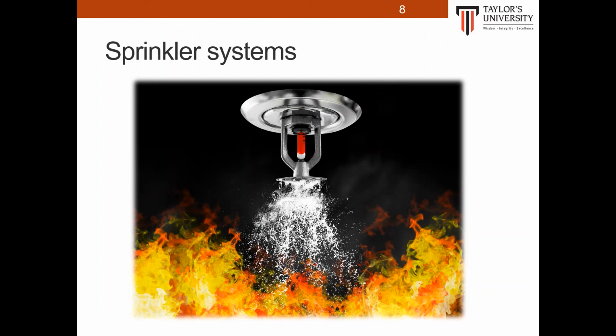Another approach activates the entire sprinkler array from a common control point. The common control point is then connected to an array of heat or smoke detectors that start the sprinklers when an abnormal condition is detected. If a fire is detected, the entire sprinkler array within that area is activated, possibly in areas not even affected by the fire.